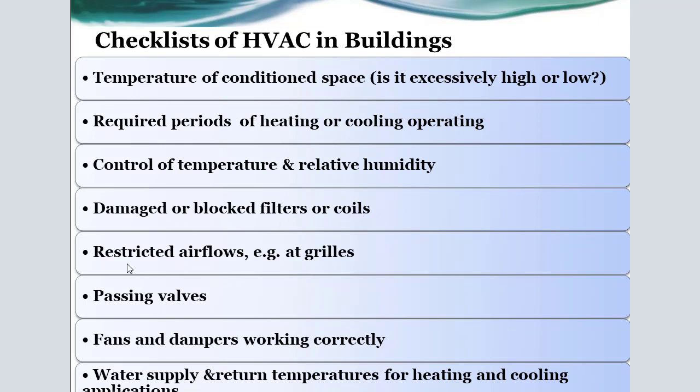Also check if there is any restricted airflow such as blocked grills, check the bypass valves, and check whether fans and dampers are working correctly or not, and also check the water supply and return temperature for heating and cooling applications.